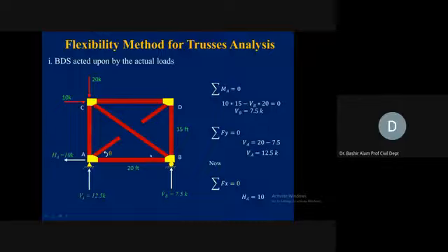Similarly, coming to AB now, if you see here, 10 we found for the support reaction. So 10 is leftward, so at A this AB force should be rightward directed. If it is away at A, at B also it will be away. Means member AB is in tension now. This gives you the direction. What will be the magnitude? Magnitude will be equal to 10 kip. So we analyzed this one also. Member AB is also analyzed.